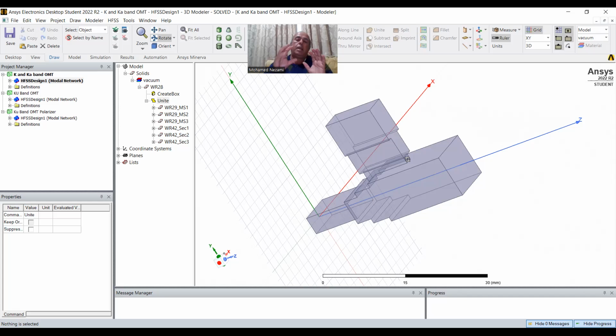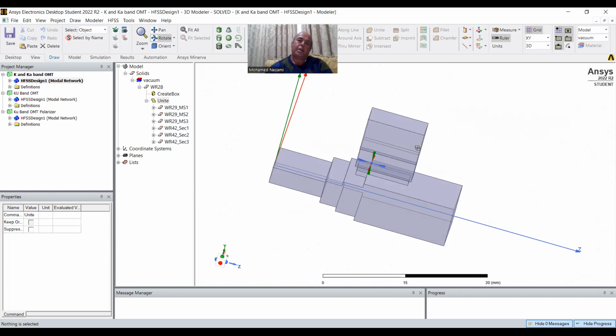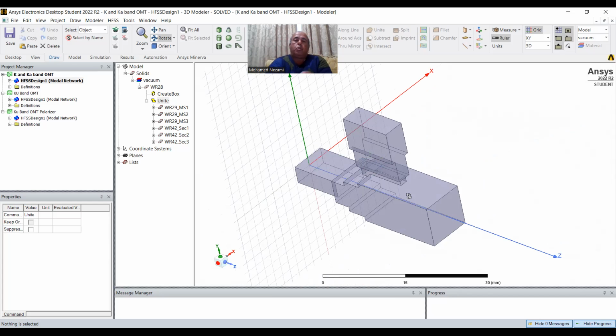and of course, a mechanical engineer will grab this, and he has to carve out, hollow this into a block of aluminum. Of course, you can't hollow it completely. What you do is you split it around the symmetrical axis, and in this case, this here, the ZY axis, okay? So you can put it into half, and then these two halves, it's so easy to CNC one half, and it's symmetrical exactly, so you only need to generate one half. The other half is exact symmetrical. So you mechanically design just one axial half of this, and you get the other half and you sandwich them together, and hopefully it will work.